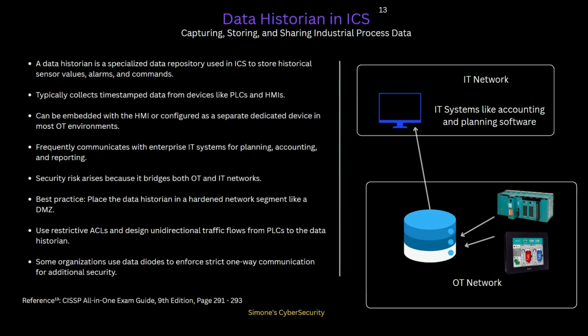Now let's talk about data historians. A data historian is like a specialized data repository that is used in industrial control systems. Just like you have database servers on the IT side, similarly, you have data historians on the OT side, in the ICS world, that capture all the data about the industrial control systems. They store values like sensor values, alarms, and commands, all with precise timestamps.